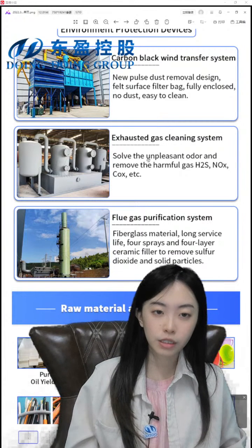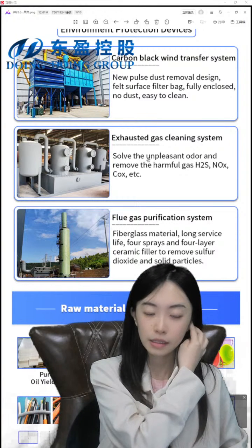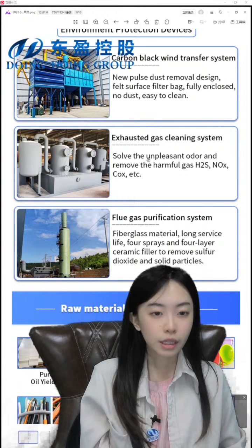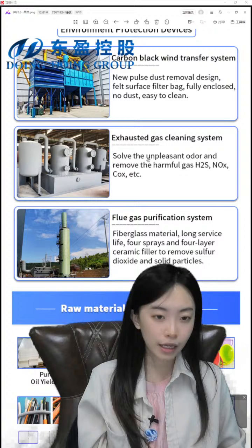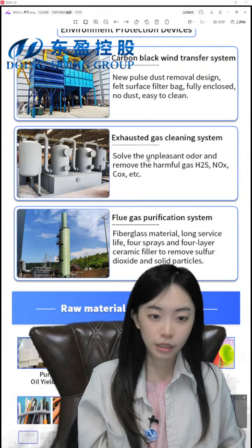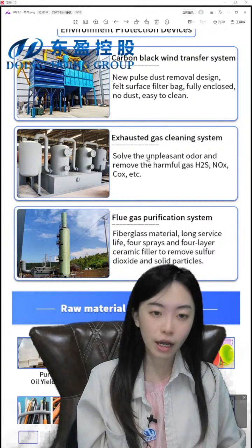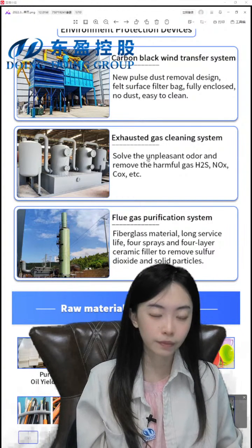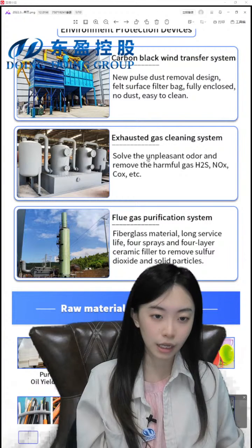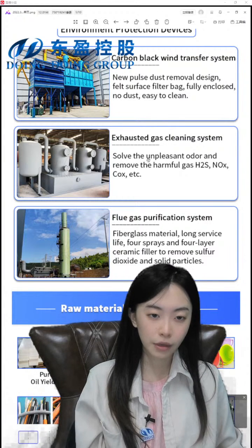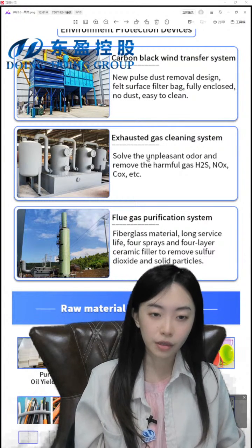But if we just reuse the tail gas, then we can save the heating energy for many days. If you choose a fully continuous one, then for the first 8 hours maybe you need natural gas, and for the next 45 to 60 days we can use the tail gas burner to burn the reactor.